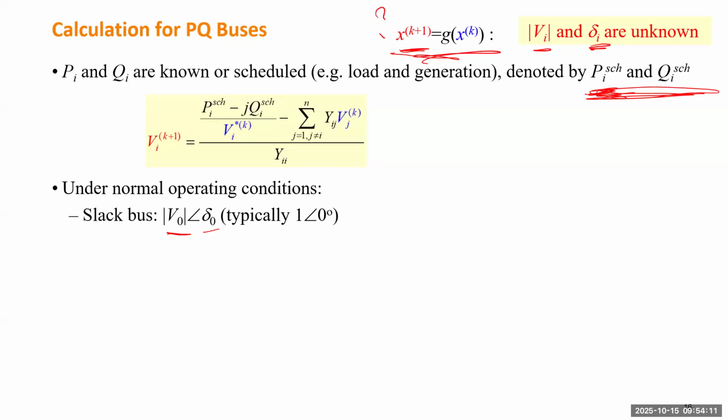For that equivalent bus, the voltage usually will be very close to a nominal value, right? 1. And you can use whatever angle for that system as 0 as a reference, because when you define a phasor, you can make any angle your reference. So you make your large system the reference. So that bus can be treated to have the voltage phasor 1 all the time.